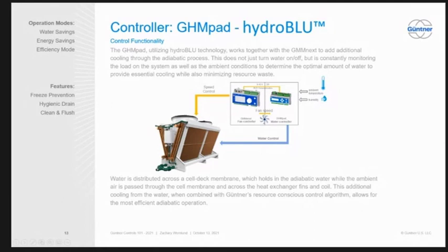Okay, the water lines. Inside of this block, we have a water meter, a control valve, a drain, and a drain solenoid. All these tie back to the GHM controller to determine how much water to put across the pads.